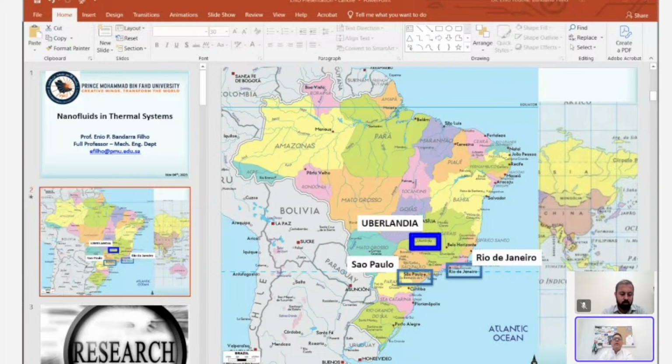Here, how we prepare the nanofluids. This is very important and understandable, because of how we can disperse the powder inside the base fluid. We have three processes. In fact, we can use sonication, where this probe comes into the fluid, and here you can see the start of the process. You can see some powder here in the top and the water here, and then they sonicate with ultrasound, and then they disperse the nanoparticles inside the fluid.